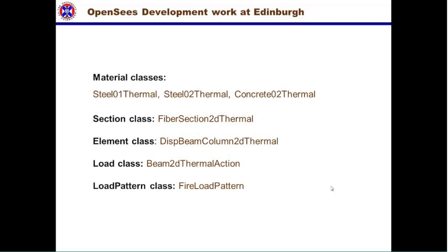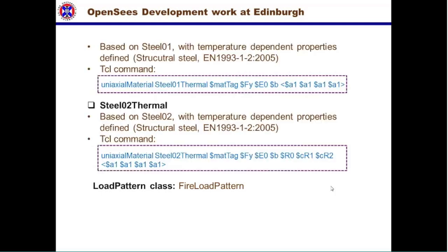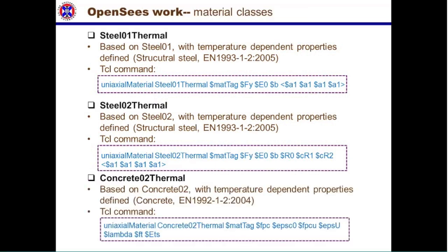For the material classes, we developed Steel01Thermal, and as we know, the steel thermal materials and the concrete materials. Steel01Thermal is based on Steel01 with temperature-dependent properties defined, which we actually bring from the Eurocode for structural steel.